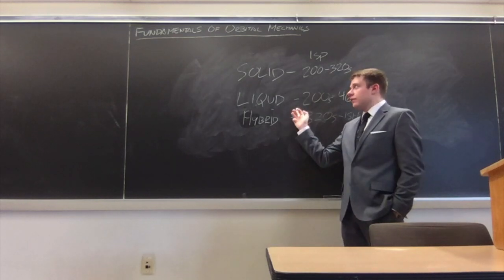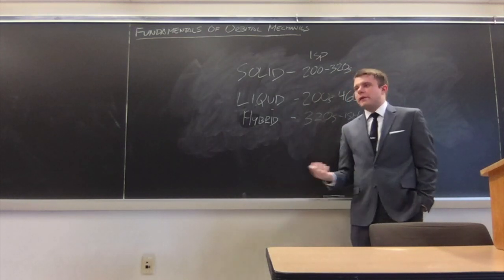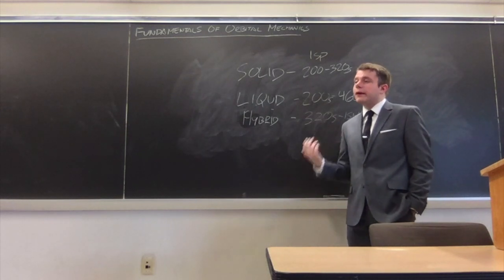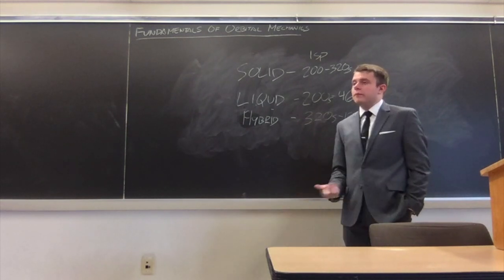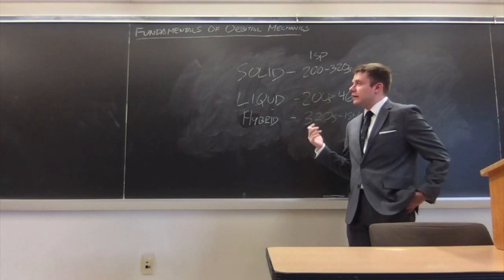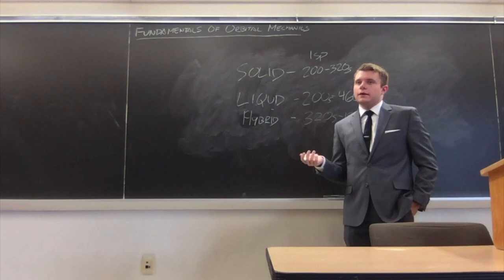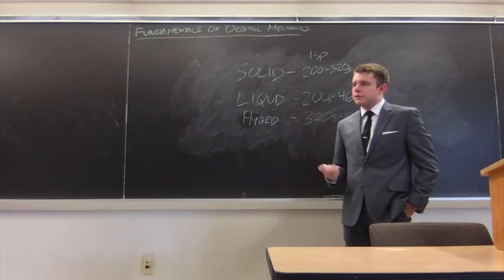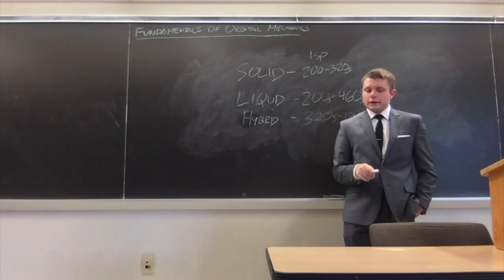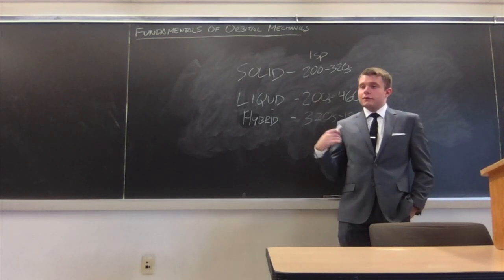And a subset of liquid propellants are hypergolic propellants, which are incredibly nasty chemicals that you don't really want to be around. They can be stored long term, but in some cases they're so volatile and so potent that they will actually eat through the propellant tanks on rockets, which means they have to be changed out very frequently. A very famous example of this is the Delta II, which was just recently retired. They had an upper stage that burned hypergolic propellants.